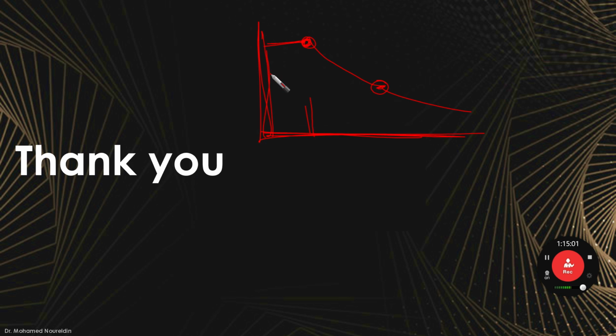And remember that we are talking about compact sections, and if we are dealing with a non-compact section, this means that the horizontal line on the curves or on the charts is going to give us flange local buckling. And if we are going to design and we find some dashed line, we can always go up or to the right in order to get the lightest shape.